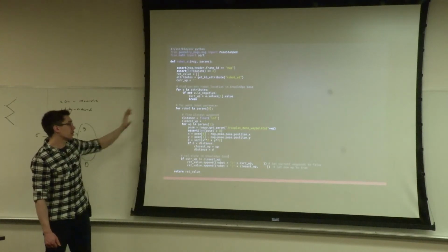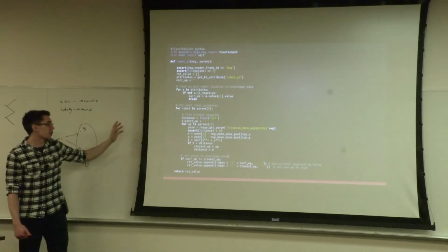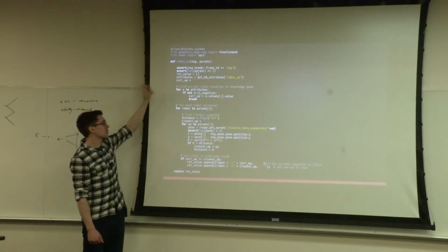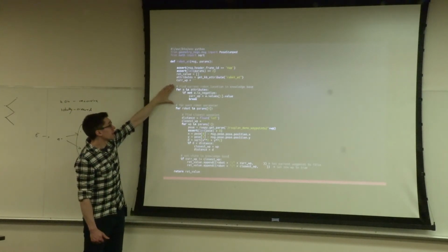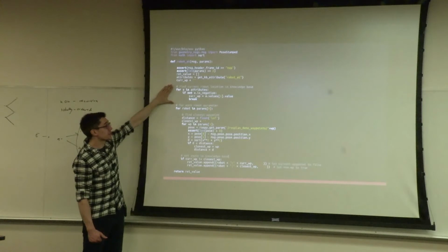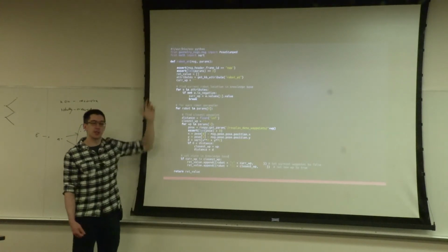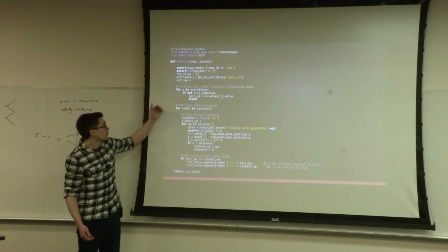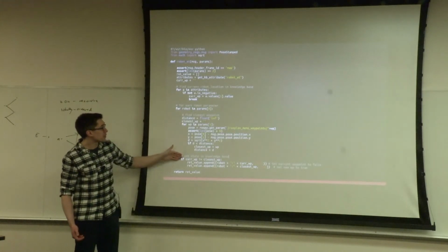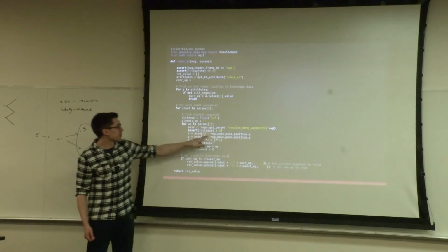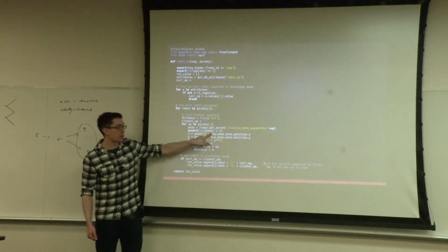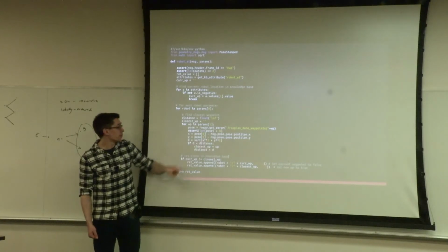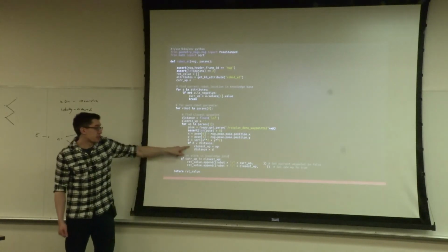I don't want to go far into what the actual code does, but it's extremely simple. It finds the current location of the robot by calling the knowledge base. In the knowledge base, the current says the robot's at this waypoint. It finds the closest waypoint by comparing the different waypoint positions with the X and Y positions from the message. And just finds the closest one.